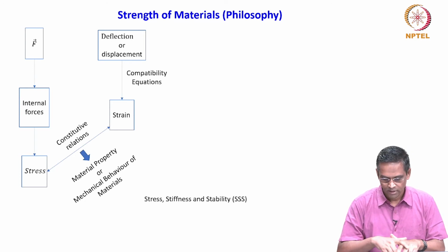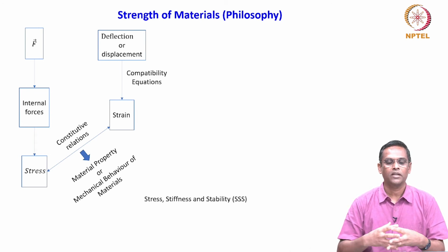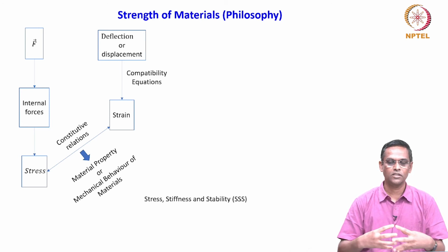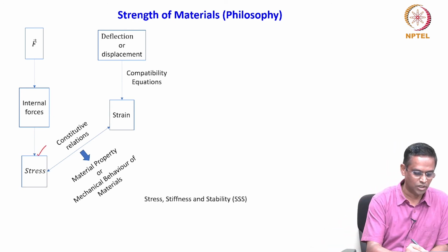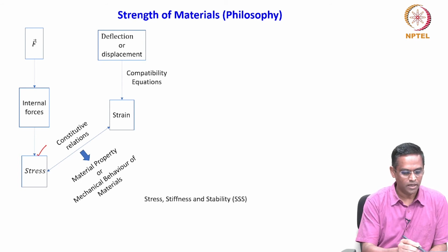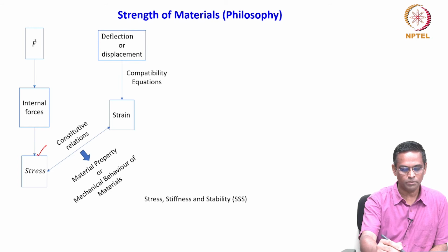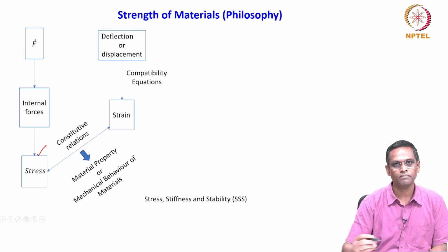And then it tries to apply the static equilibrium equations, where a body is subjected to an external force, and the resistance from the body, the internal forces, is being measured as stress. But then, as I just said, stress cannot be experimentally, physically measured. So, we look at the deflection or displacement, then we measure a strain, and we have the constitutive relations between stress and strain.